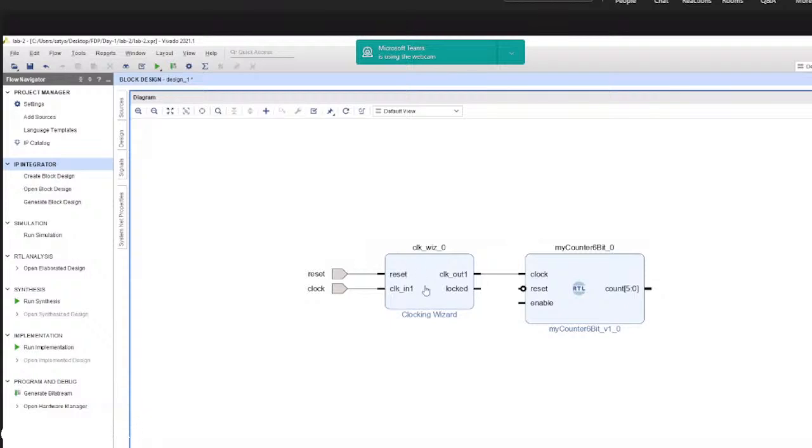Now I told you this clocking wizard will be able to generate any clock signal with the desired clock frequency. So how is it able to generate? Inside it, on the FPGA, it will use a PLL, that is a phase locked loop. It is just a programmable clock frequency synthesizer. Once you have given your desired clock operating frequency, the PLL will be configured to generate a clock signal with that desired frequency. I think you might be aware of the PLL mechanism.